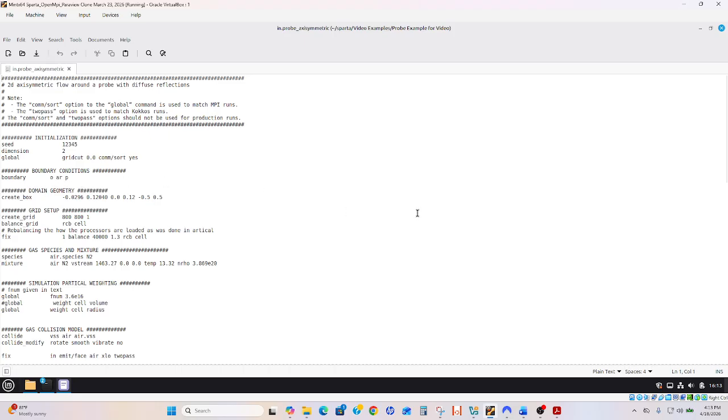And this is the way it seems that they did it in their article, and I tried to mimic everything I could. It's got the same grid size, 800 in the y direction, 800. I mean, in the axial. I'll start calling it axial and radial if I can, but 800 in the axial direction, and then 800 in the radial direction, and then one, of course, in the z direction, because you always are having to define that other dimension.